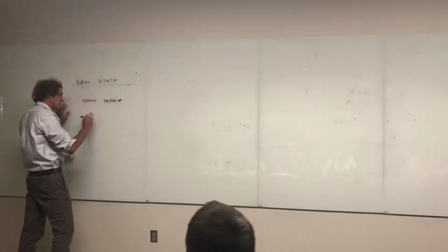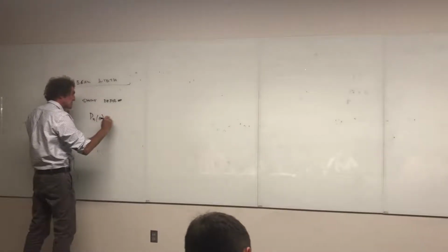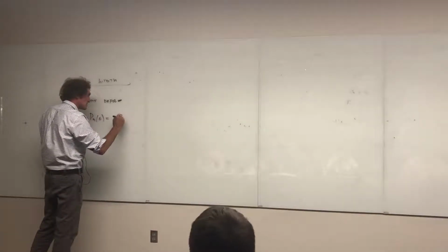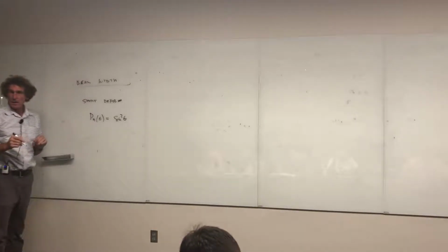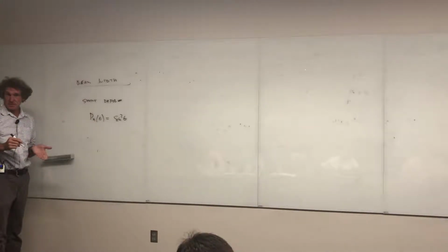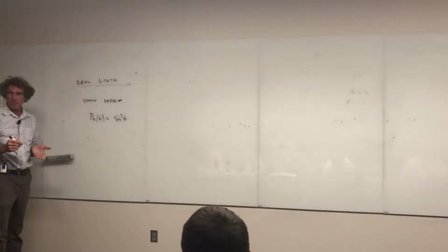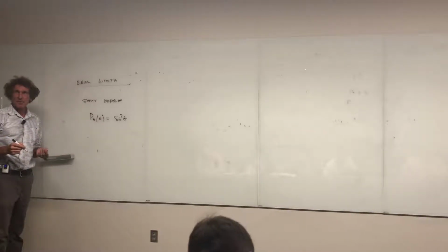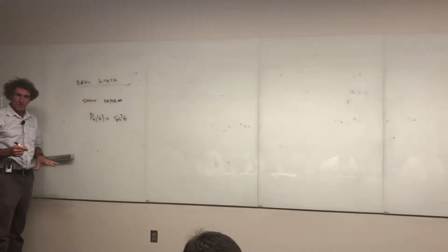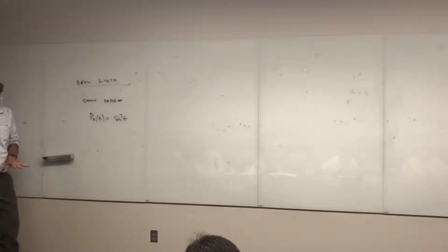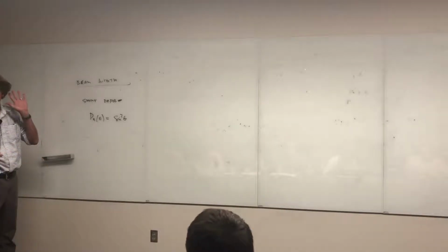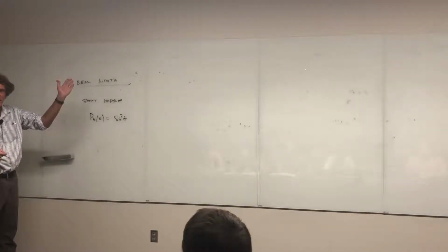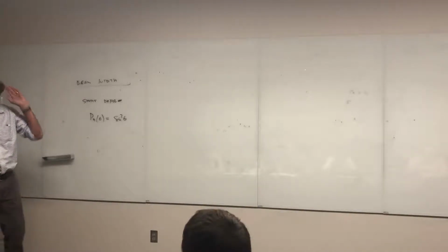Remember how the normalized power density was just equal to the sine squared of theta? So you get the normalized power density when you do a beam width. And this is called the half power beam width or the full power beam width, but these are just terminology. It's always with power, never with the E field or the H field, almost never. I say that, and then there's going to be some weird article in a scientific digest that looks at the E field's beam width. Most of the time we talk about power.